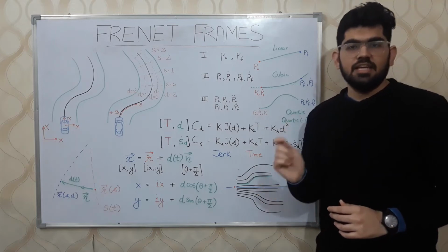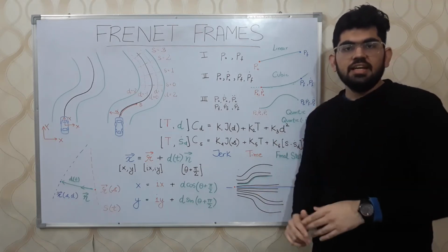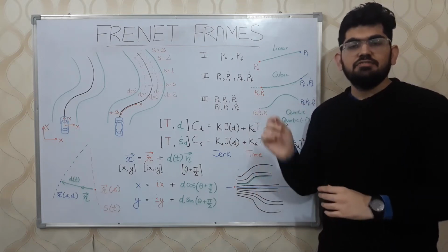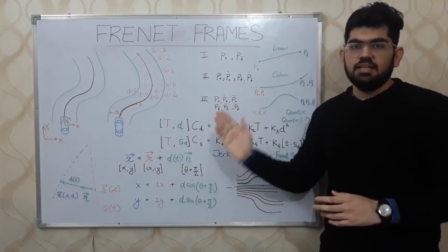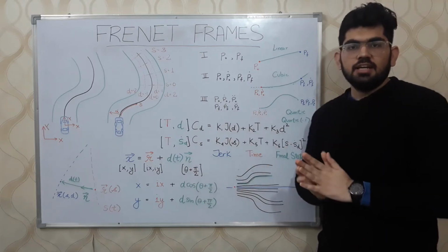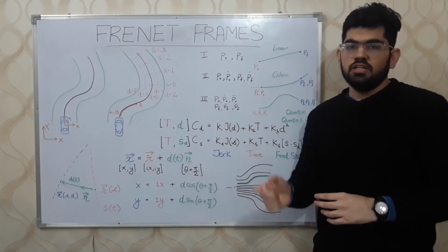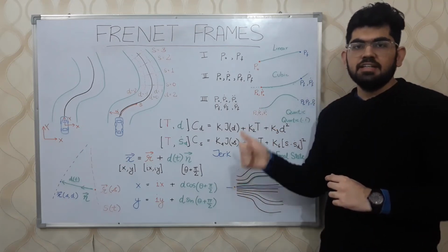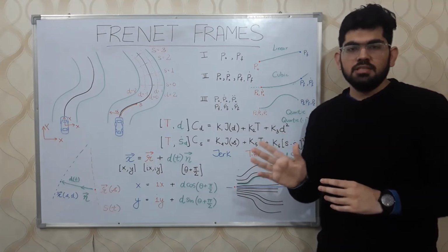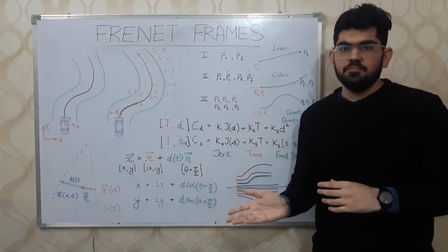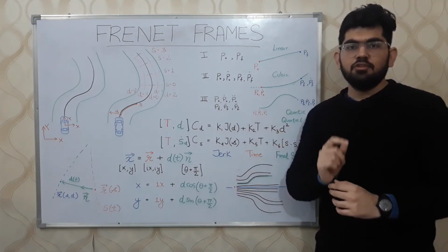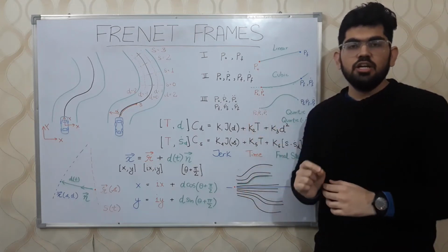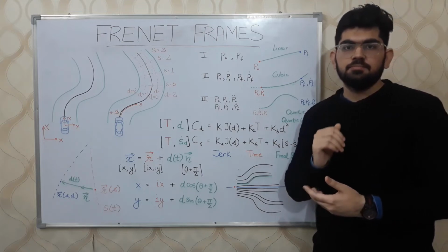To generate a number of different polynomials in the s direction, we vary the final velocity and the time. If we want our car to maintain, let's say, 40 kilometers per hour, then we are going to vary the final velocity by approximately 10 to minus 10 units. Hence, starting from the range of 30 till 50 kilometers per hour, we are going to generate different polynomials.